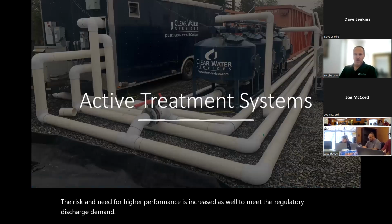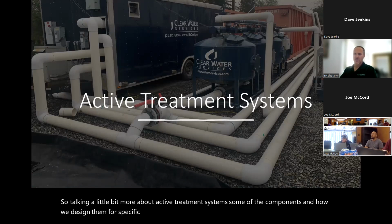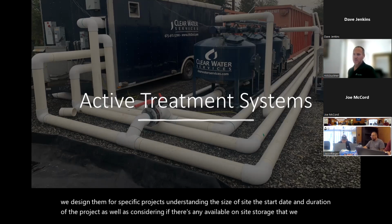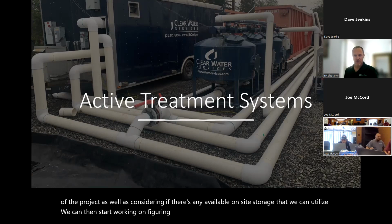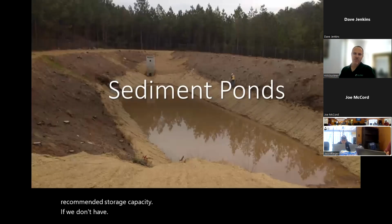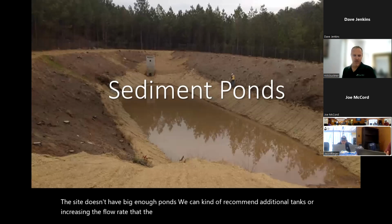So talking a little bit more about active treatment systems, some of the components, and how we design them for specific projects, understanding the size of the site, the start date and the duration of the project, as well as considering if there's any available on-site storage that we can utilize. We can then start working on figuring out a suitable system flow rate and a recommended storage capacity. If the site doesn't have big enough ponds, we can recommend additional tanks or increasing the flow rate that the CESF system can hit.